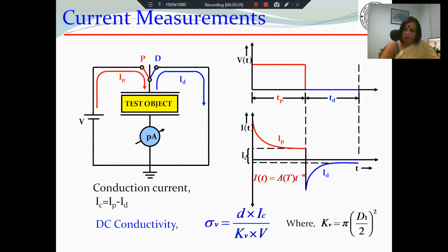But in this long drawn out procedure, if we wait for sufficient time and choose our poling times and depoling times wisely, we should be able to register the entire current that flows through the circuit to establish the polarization mechanisms, and similarly the depolarization mechanisms. This polarization current and depolarization current measurement can be used to understand and analyze the polarization mechanisms in the sample.